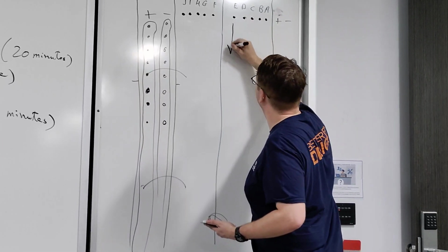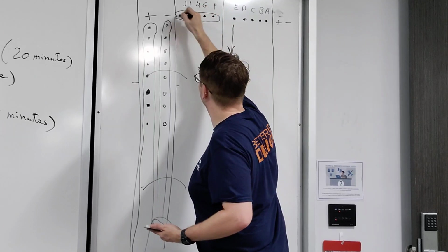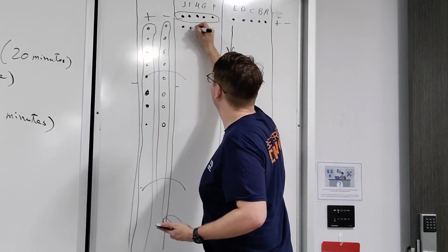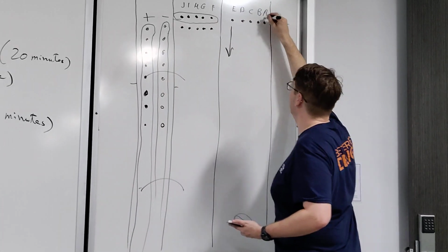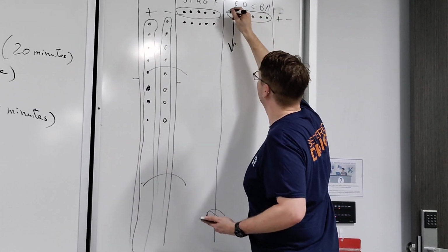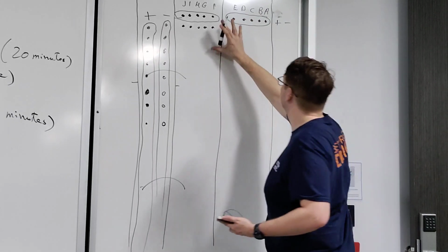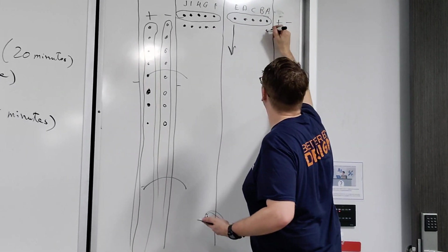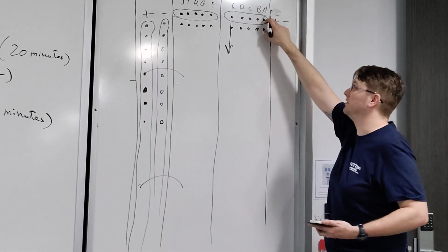And that's repeated all the way down. These 5 are connected, but only these 5. So the next row down, there's another row of 5. Those are not connected. These 5 over here, even though they're right next to these, they are not connected. This gap in the middle is there to indicate that they're not connected. And as I said, the second row is also not connected to this top row.